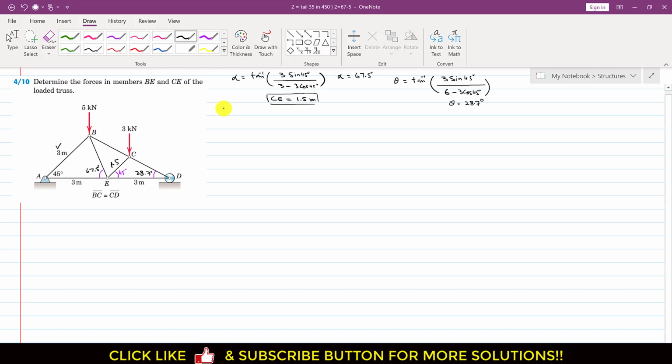Now we apply the summation of moment at point A equals 0 to the whole truss, right? This 5 kilonewton force is producing a clockwise moment about this point A. Let's say the counterclockwise moment is positive, so I will write minus 5, and the perpendicular distance of this 5 kilonewton force from point A is this much, at that similar H point, so this is the cos component: 3 cos of 45 degrees. Similarly, this 3 kilonewton force is producing a clockwise moment about point A, so I will write again minus 3, and the perpendicular distance of this 3 kilonewton force from point A is this much distance. Let's say this is point G, so this AG distance.